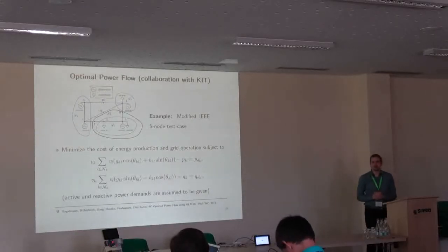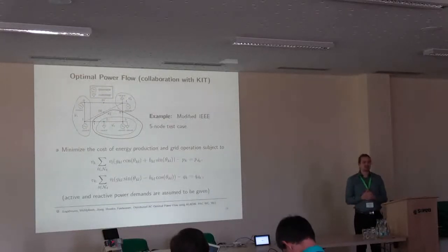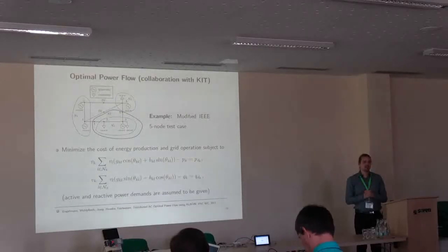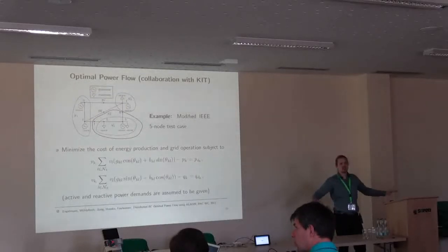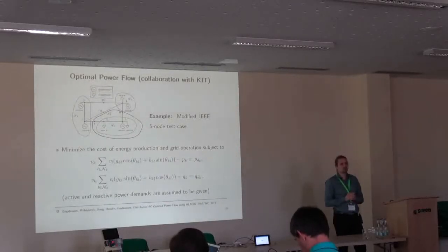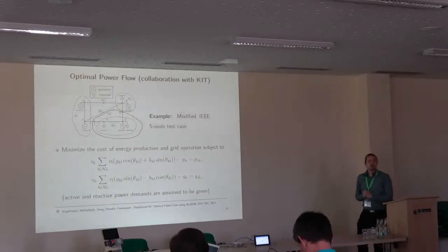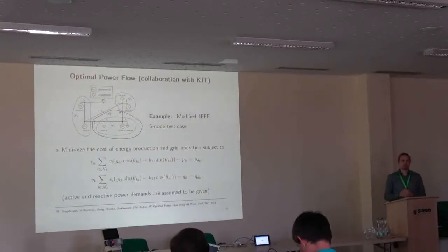That's probably a different approach to what Sigurd said today in the morning, right? We are trying to extend the optimization framework eventually to plant-wide control. We don't have case studies for this yet, but I think it could be a viable path. If we have all these small controllers which use their own NLP solver to solve small, easy optimization problems, and Aladin is capable of bringing this together to solve the plant-wide optimization problem, I hope it may lead to some results or overcome the big difficulties that we have at the moment with the centralized solvers for these big case studies.